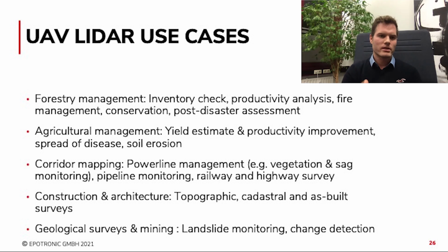So what is this overview here? Just to take away the burden of the high costs of an initial LiDAR procurement. We have the setup cost, meaning the hardware, the software, also the training, all these kinds of things for the equipment, for the GNSS rover, for UAV photogrammetry, and for UAV LiDAR. UAV photogrammetry, Alex, I think that was a Phantom 4 RTK. Yeah, that's right. And the UAV LiDAR? That was the LiDAR V70 with the M300 RTK. Okay, so you see it's quite a mix of technology.